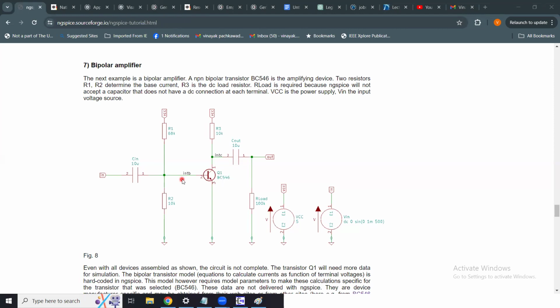So the basic components of this circuit: you have this transistor, which has a collector pin, base pin, and emitter pin. The circuit is biased in the common emitter configuration because the emitter is connected to the ground here, and you apply input to the base emitter side of the circuit, and you take the output from the collector emitter side of the circuit. So that's why the emitter is common with respect to base and collector. Okay. And R3 is your load resistance. R1 and R2 are used to set the DC operating point of this circuit.